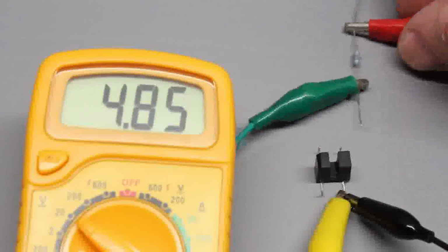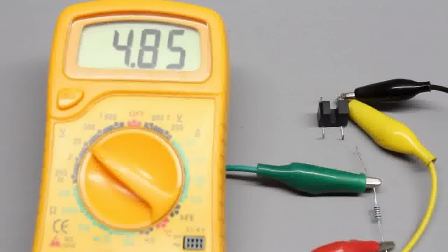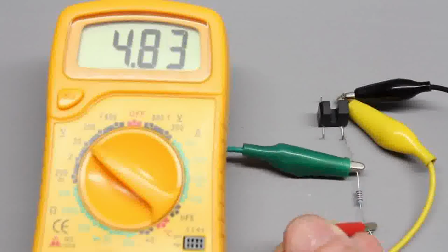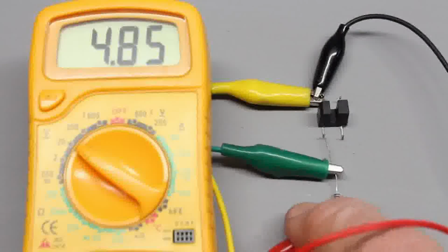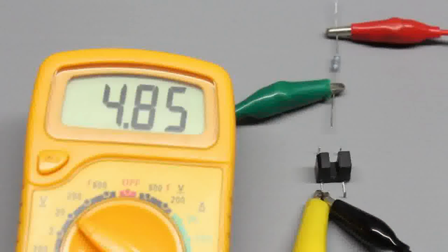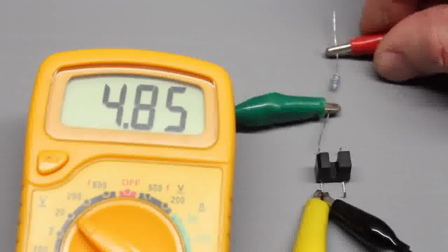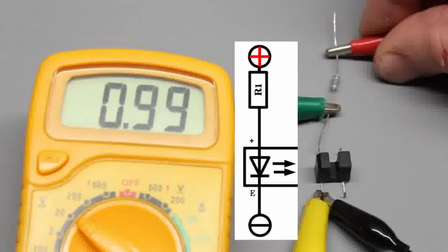The voltage across the pins is recorded while the optical sensor gets connected to the DC voltage through the series resistor. We get 4 variations of the pin configuration, by what we can read nearly 5V at 3 of them, and finally one configuration with a clearly lower voltage drop, we get a reading of 0.99V. That's the LED side of the device in forward configuration.